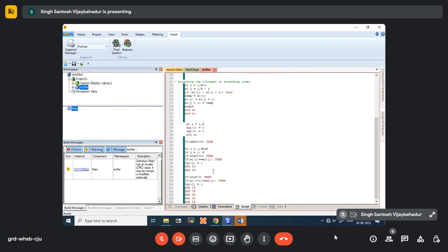All performance will be done, and the loop is closed with if and if. The second case is if IA is less than zero, then what? If IA is greater than zero, turn on the switch which has the least voltage, which contains the capacitor having the least voltage. If IA is less than zero, then turn on the capacitor which has the highest voltage.